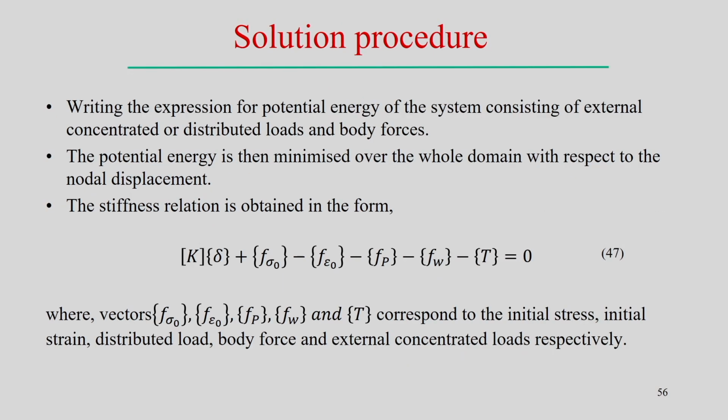Now, a similar solution procedure follows: the potential energy minimization, consisting of the external loads, concentrated load, distributed load, and body forces. If we consider this particular situation and follow the potential energy minimization, we have already shown how it leads to an expression between the nodal displacements, and finally the stiffness relation in the form of a matrix can be represented like that.